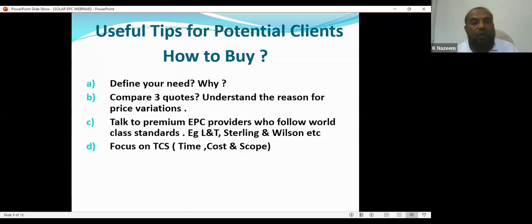Now you put a 5 kilowatt power plant. So it will generate almost around 600 units per month. So out of 1,000, 600 units will be deducted from your electricity bill. You are supposed to pay only the cost of 400 units. So this could be the second reason.